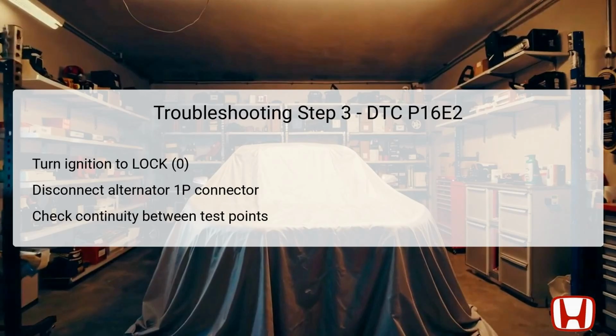This step helps to ascertain whether the LIN circuit shows continuity or if there is a potential short in the wiring that could prevent proper communication. If continuity exists, proceed to the next step. If not, it indicates a break or short in the LIN circuit requiring further examination.